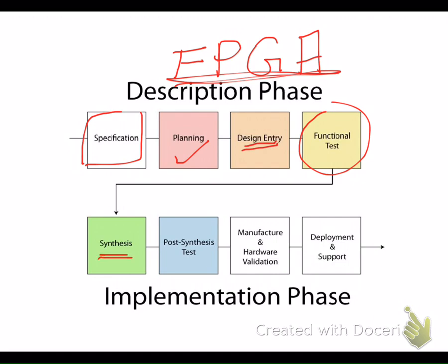So assuming you decide to go with the FPGA, of course, as we will see later on, you can write a code, but unfortunately this code cannot be downloaded over the FPGA, because in our terms we call it non-synthesizable. You cannot synthesize, unfortunately, that code over the FPGA. It can't happen, and we'll see some examples on that. It's not possible.